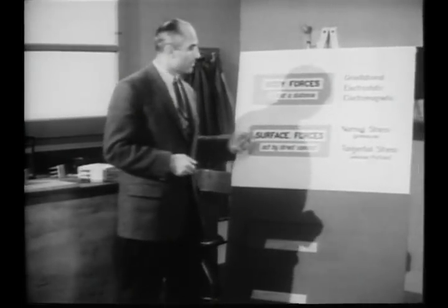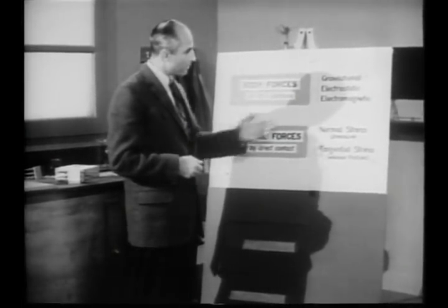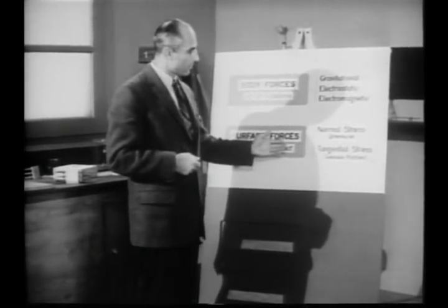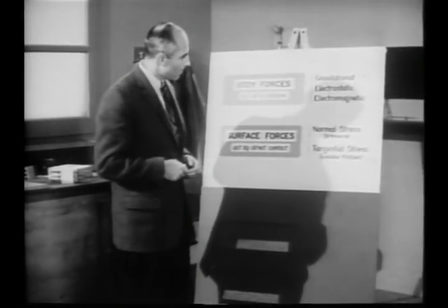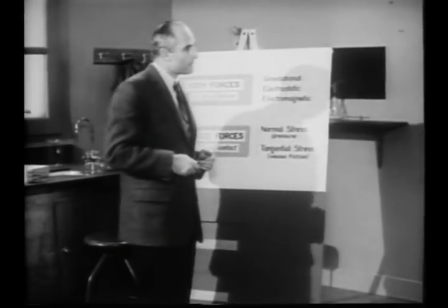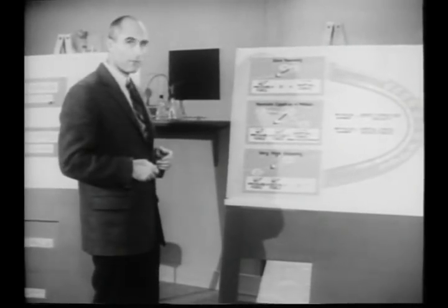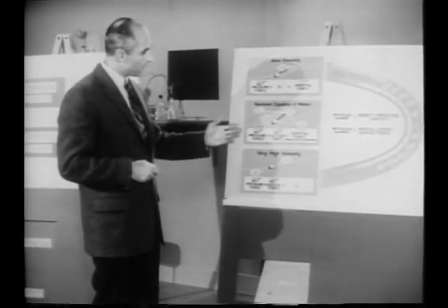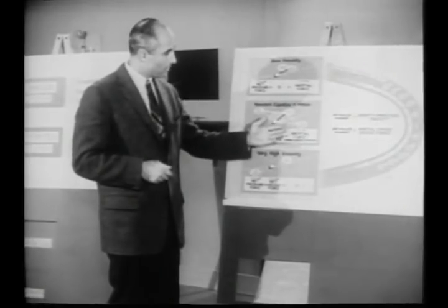We resolved the surface forces into two components: pressure forces acting normal to the surface and viscous forces acting tangentially to the surface. We saw that these forces control the motion of a fluid particle through Newton's law, which relates the net pressure force on the particle and the net viscous force to the inertial resistance to